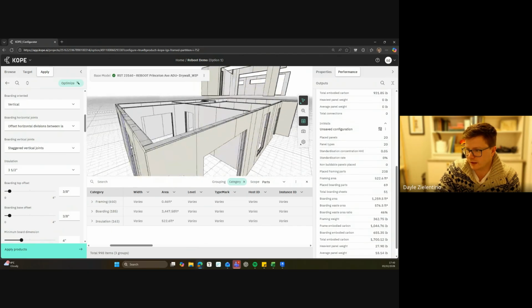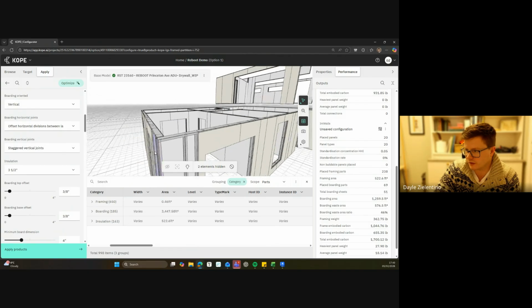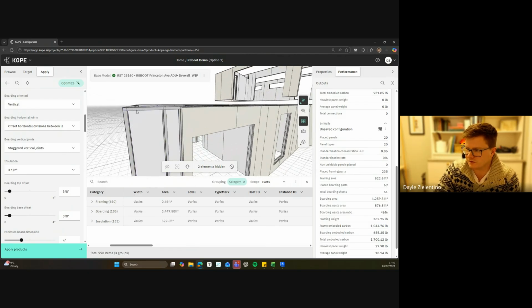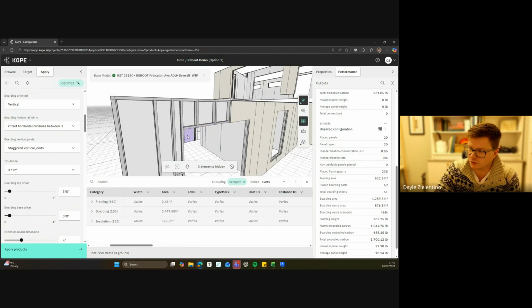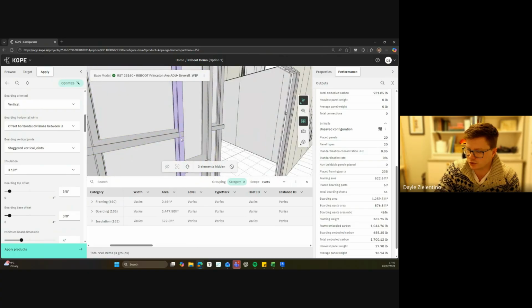So what we can do, again, we've had another customer with their activity say that the way that Cope understands this is a top track, this is an end track, this is a stud, this is a jam stud, a header, a king post, a noggin, whatever. What we can do is then encode that for every junction that Cope generates, increase the count to 2 screws.